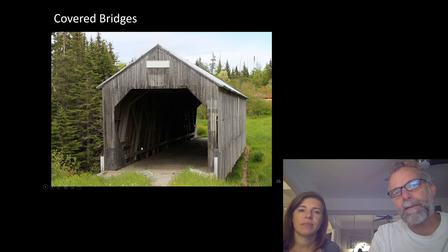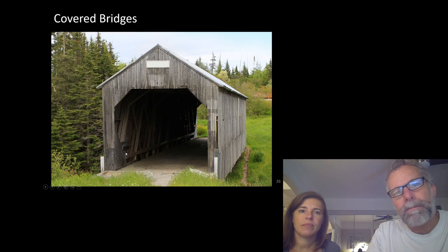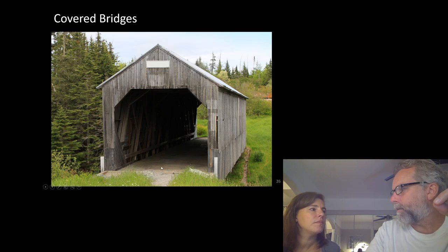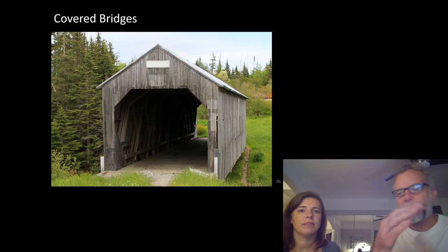This one is designed to carry compression, but only very nominal compression, because generally the loads are down. And the tension members are all vertical. These rusted lines are the vertical rods. These are extremely pragmatic from an assembly point of view and a connection design point of view. They look more complicated, with lots of different pieces going this way and that way and slipping past each other.